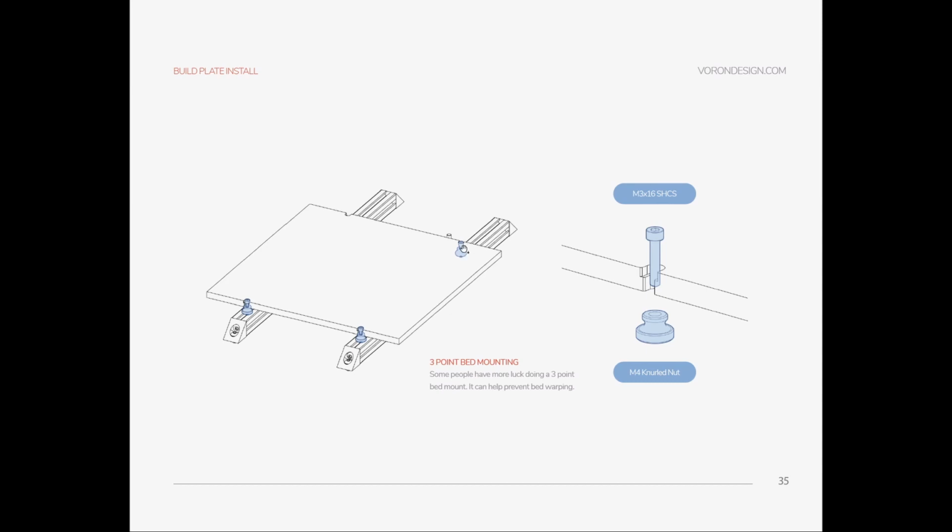However, I didn't tighten all four of them, or all three of them, but again, my bed is now not that flat. It's showing me a 0.2 difference in the corners. I'm not sure. Maybe the heat cycle caused that. It's not a good one. I'm not sure. Yeah, but like I said, heat your bed and wait for an hour or so.